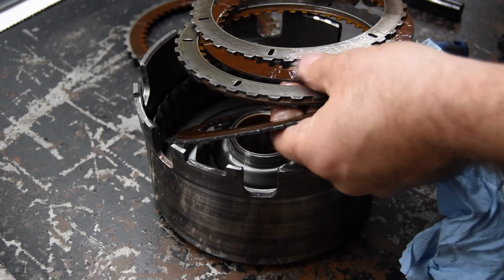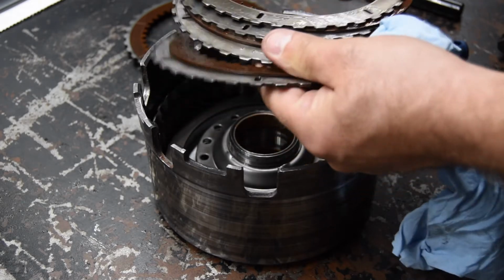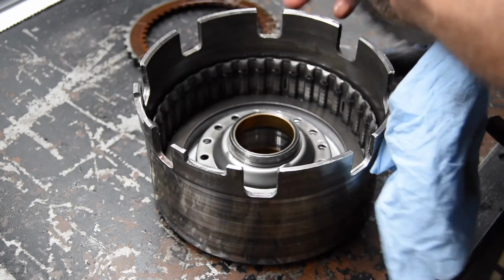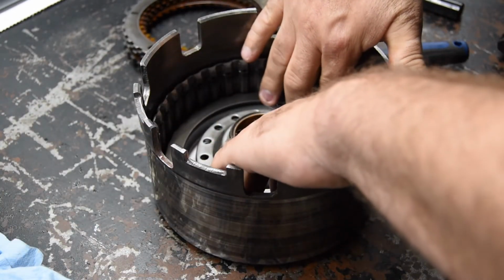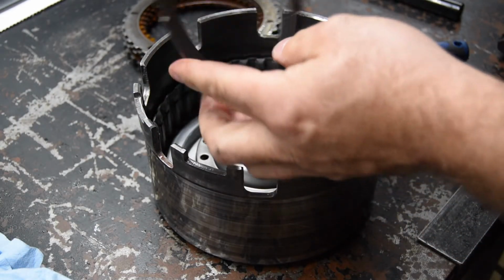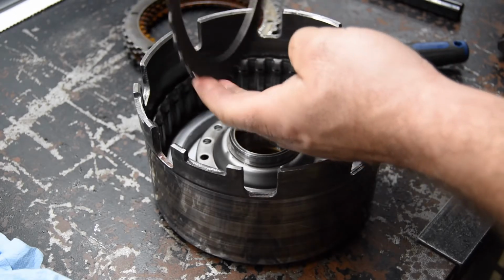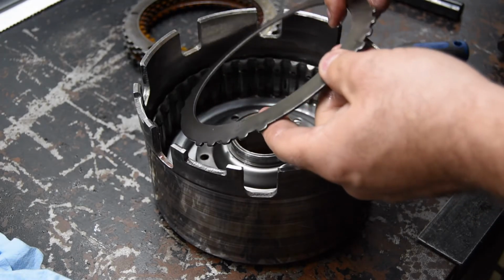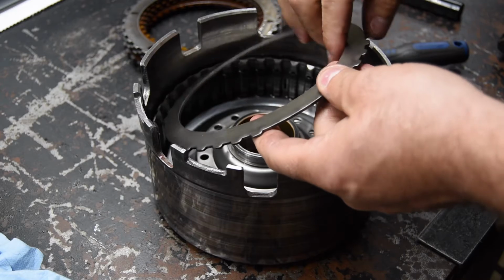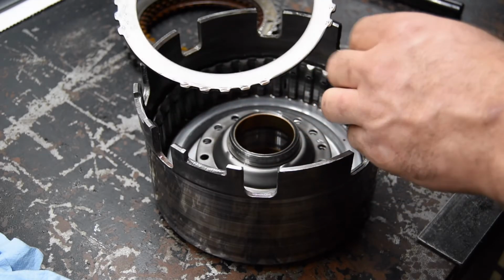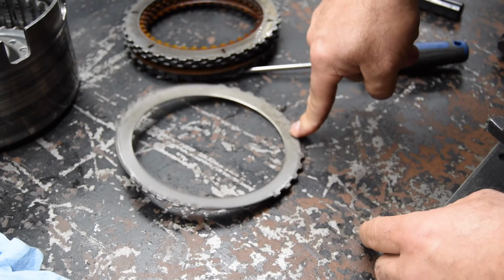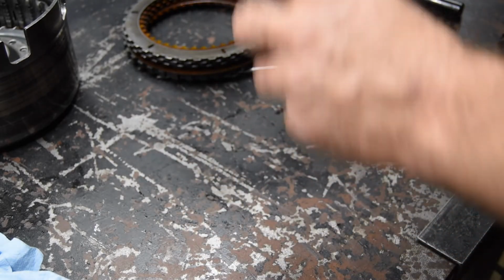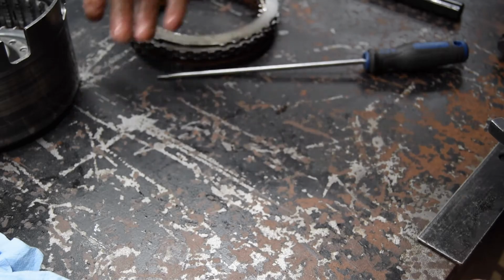This one here happens to have 1, 2, 3, hold on, let me count. There's 4 clutches and 4 steels, 1 pressure plate. And then on this last one here, we have a spring. Now this isn't necessarily a wave spring, but this is actually a Belleville spring that acts just like a wave spring. So this one isn't flat. If I were to put it down on the table surface and just push on the edge, we see it lifts up, and it performs the same function as the wave spring.